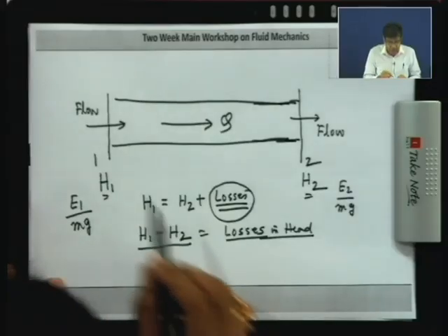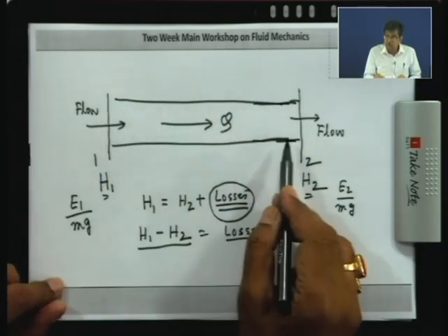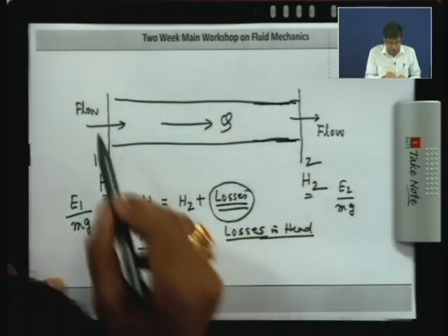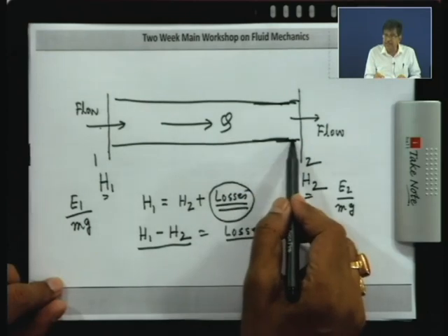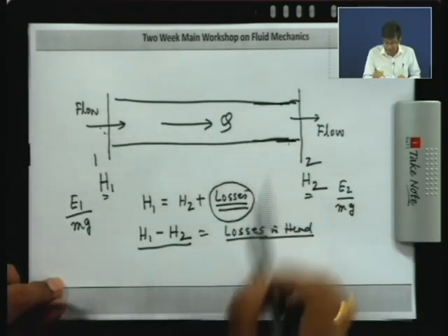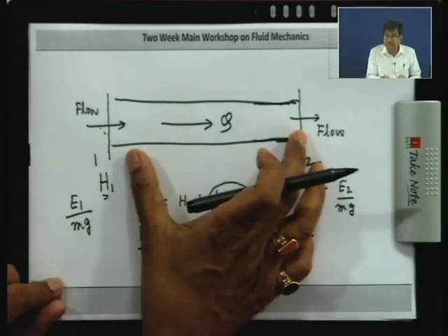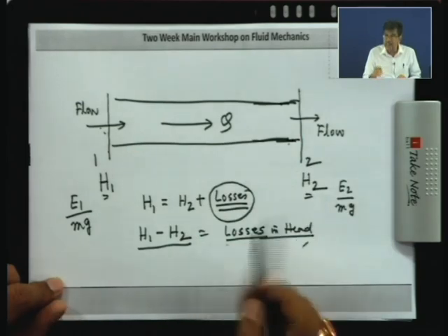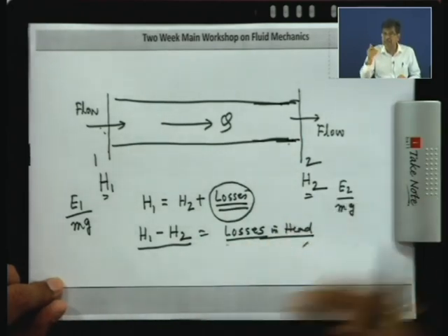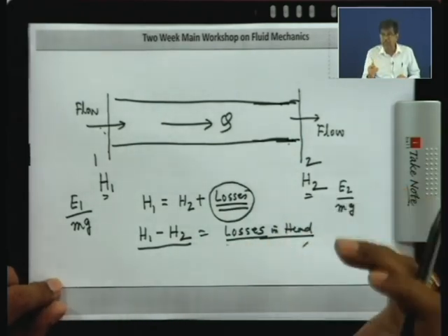So, this is the basic concept that whenever we solve any pipe flow problem, we must see what is the energy difference at inlet and outlet which causes the flow, this energy gradient, and this must be overcome by the total resistance suffered, that means losses in head. That resistance actually converts this energy into intermolecular energy, which we conceive in terms of the loss.